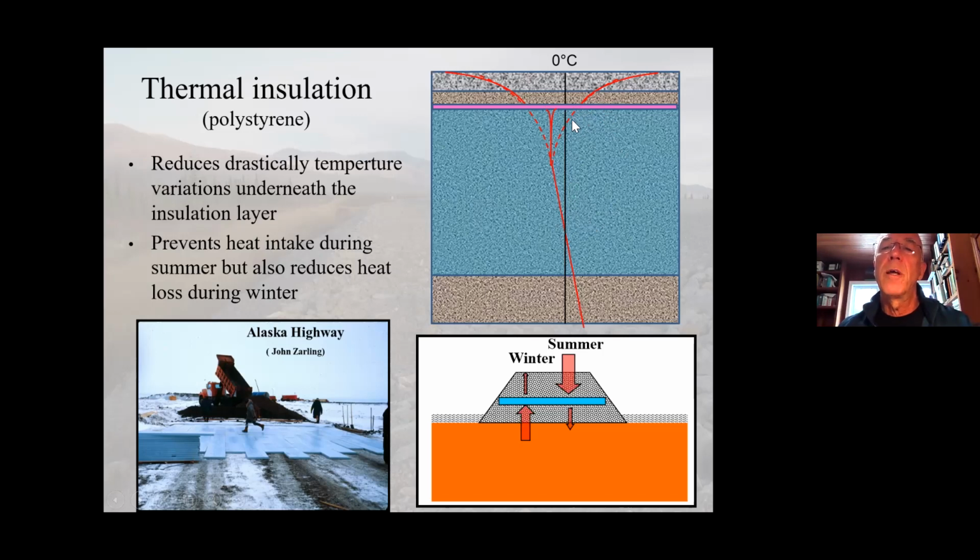And the latent heat that's contained in that thawed ground is never going to escape the system, and you're going to end up with something messy. So insulation needs to be placed in the winter when you're in cold conditions to avoid that problem.